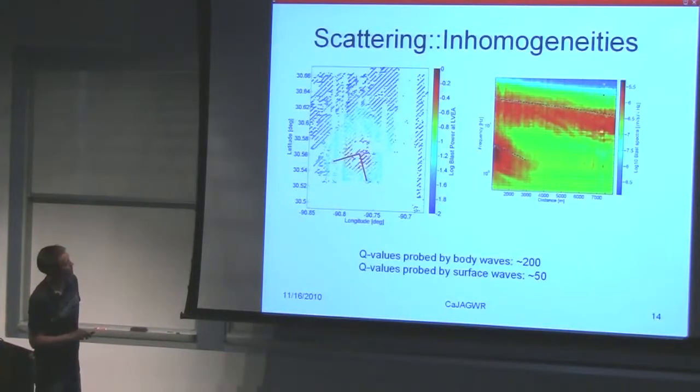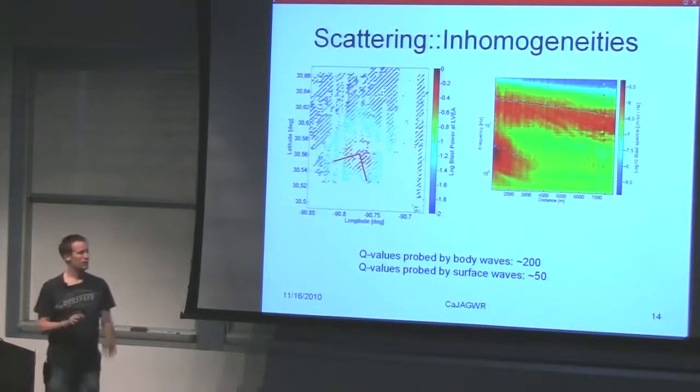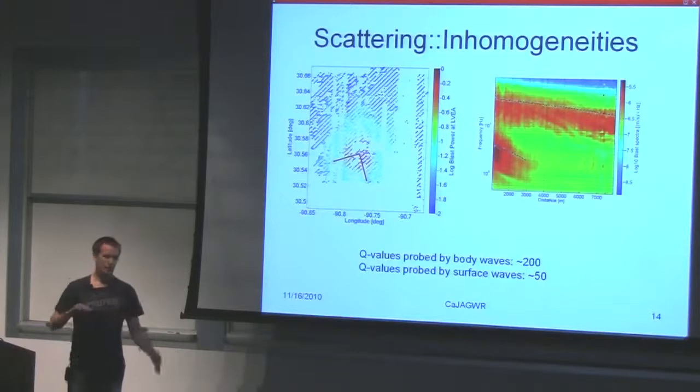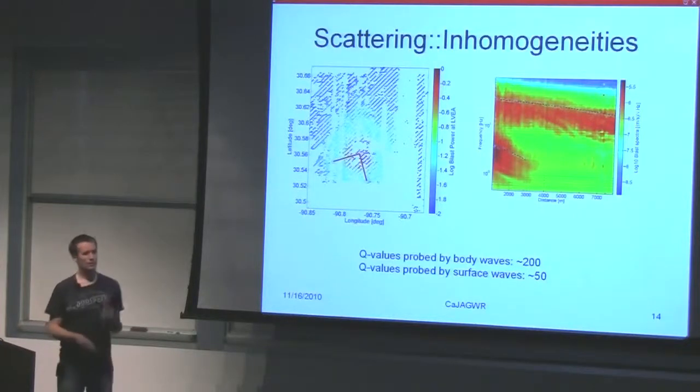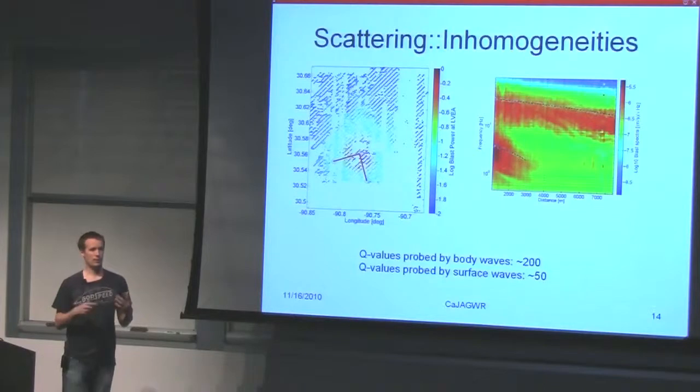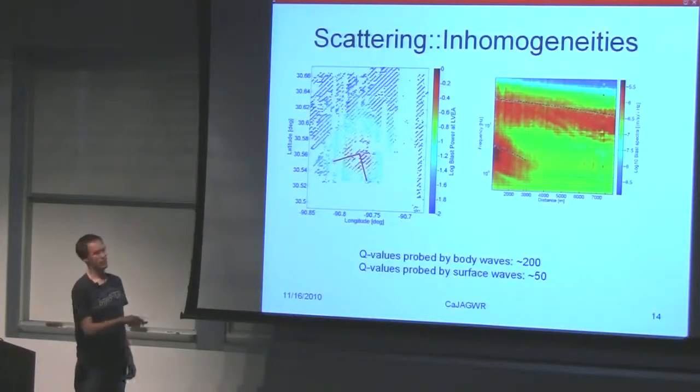And we did that for the body waves and for the surface waves, and we found two Q values. It then turned out, at that time we didn't know, but it really turns out to be typical. The hard rock always has hundreds for the Q value, and the near surface layer, the weathered, unconsolidated part, always has about 50. That's quite typical, unless you are really considering sand or something, which is a little bit messy. But if you go into hard rock, which is not sedimentary but something like igneous, really strong, then you can usually get Q values of 1,000.